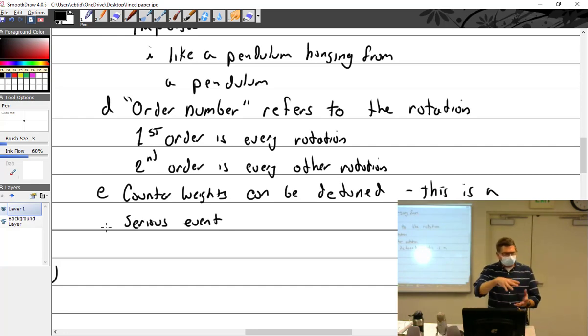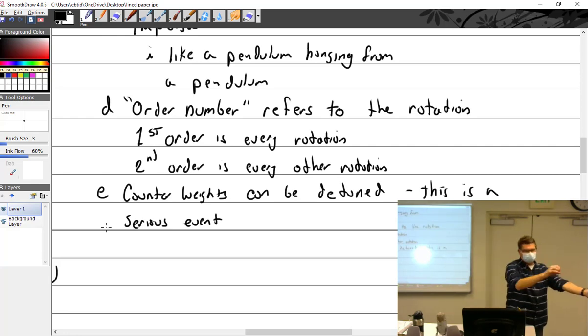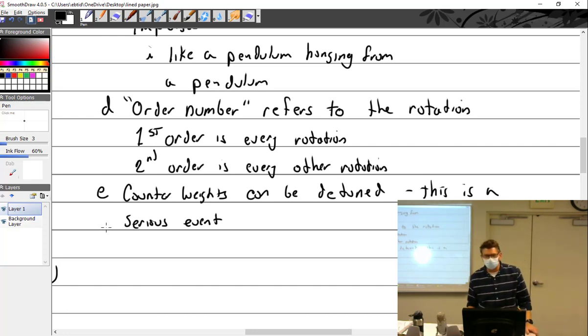And as they pulled the cowlings off to get to the engine to take it out, the way big Continentals are, it's not like your Lycoming, which has 4 holes in the back of the case, and the motor mounts come up this way and this way. Well, a Continental has a bed that goes way out, and then it's got 4 legs, 1, 2, 3, 4, on this bed that goes out. Every one of those legs, they said it looked like a laser had cut through it perfectly. Every single one. There was nothing left holding the engine in but the cables and wires.